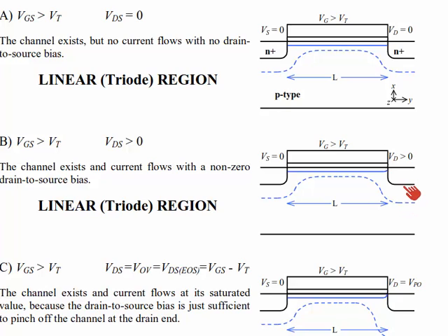So if you look really carefully, you'll see the depletion layer between the drain and the body looks a little wider than the depletion layer between the source and the body. A subtle effect also happens as we apply, first an obvious effect and then a subtle effect. If we apply drain voltage greater than 0 to the drain relative to the source, we expect electrons to flow toward the drain. The positive voltage attracts electrons. We get current flow in the channel, so a non-zero current should flow.